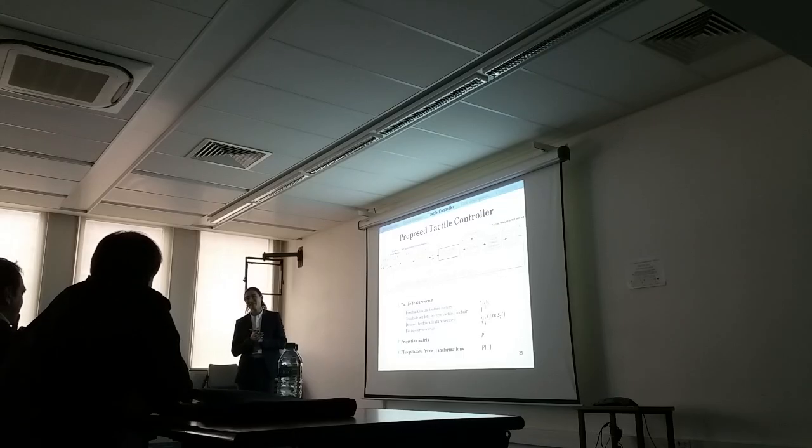And the projection matrix, this is the selection matrix, no? No, it's also a selection, but at the same time, in order to perform the co-manipulation tasks, it maps one feature error to another Cartesian space error. So this is also like projecting. It's not only selecting. We project one feature directly to another.